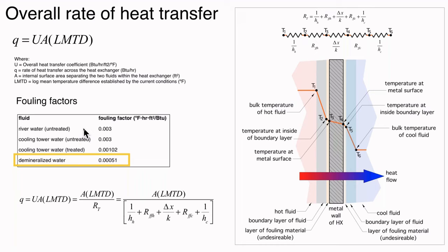So it's important to keep the surfaces of these heat exchangers, the internal surfaces, as clean as possible. Demineralized water is certainly one way to do that. If the makeup water in the system has high total dissolved solids content, you definitely want to treat that water before you put it in the system. And also other debris, dirt debris or iron oxide, we don't want those films to form on the inside of the heat exchanger.